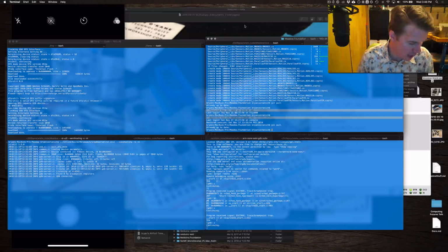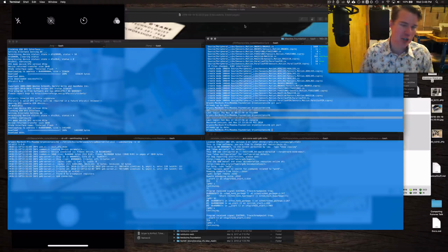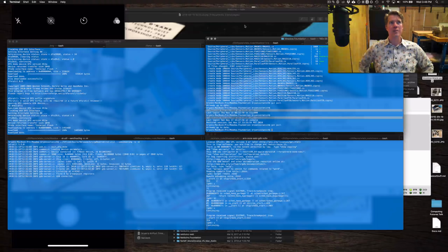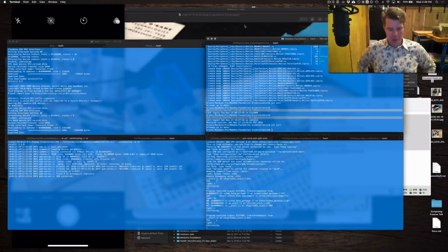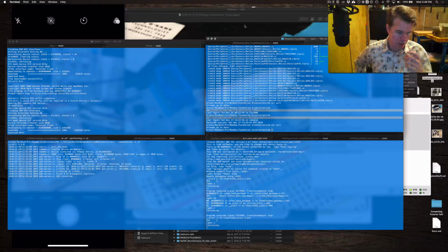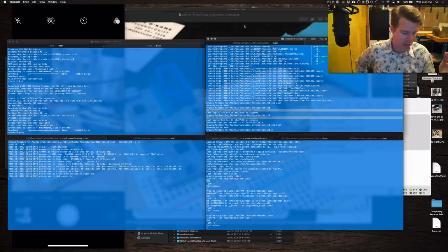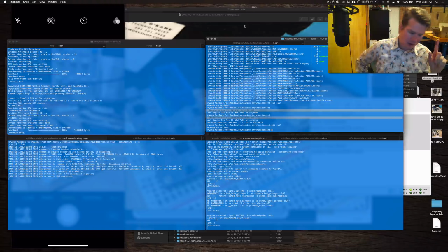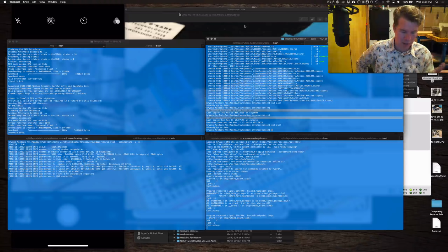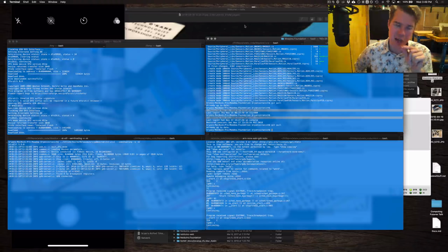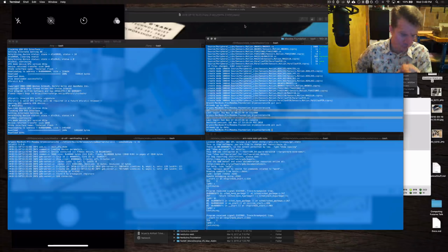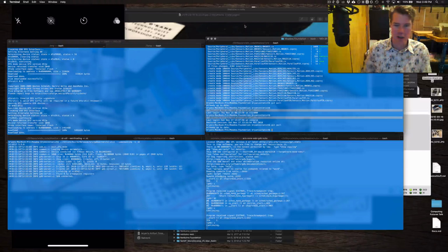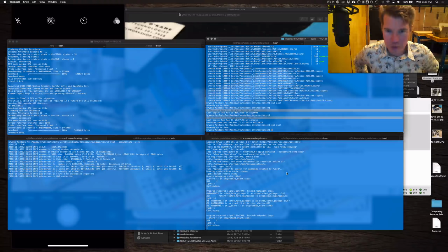The other thing we use sometimes is ST Flash. This has the upside of not needing to put your device into DFU mode. It's listening, and you can send it over and flash it anytime you want. If I recall, that goes over JTAG in our setup. I may be confusing that, but I think it's over JTAG. The problem is it's not as reliable as DFU, but we do need JTAG to do real-time debugging of the OS, and we use the GNU debugger to do that.